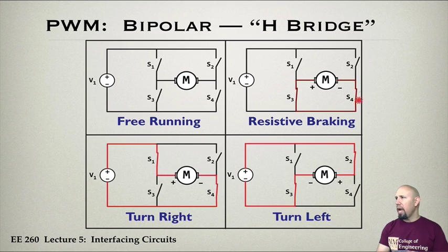so that you can actually brake faster. So in this configuration, friction in the system will cause the motor to eventually stop. In this configuration, you not only have the friction, but you also have the resistance that also dissipates energy. So in this case, this will stop, but it will take a longer time to stop, depending on the inertia of the system and the motor. In this case, when you stop, it actually provides kind of a braking action. It's not exactly a brake, but it's noticeable. This configuration will stop much faster than this.